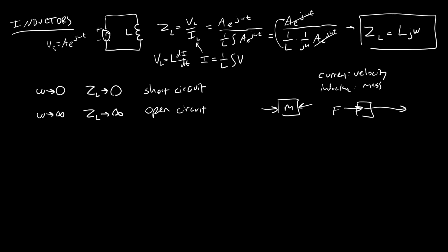If you just keep applying a higher and higher frequency signal to an inductor, then it's going to act like an open circuit. And this becomes relevant later when we talk about motors and why motors take time to start up. Just think of a motor like having mass. It takes time to accelerate a mass. Well, it takes time to start up an inductive load like a motor because, again, at high frequency, if you have an instantaneous or very fast change in something, it's acting like an open circuit.